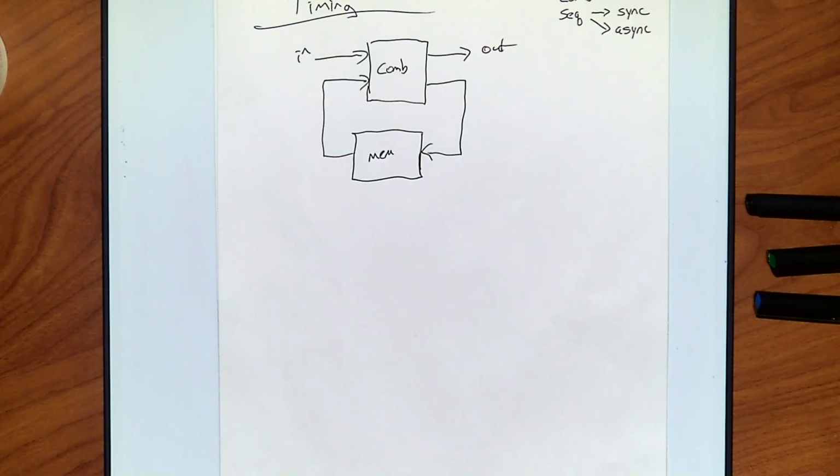So in essence, that XOR becomes a flip or not flip based on whatever the data line is. Usually you just add an XOR and you get a T flip-flop. That's useful for counters because when you're counting, something's constantly changing, so you can just send the T signal, which means keep counting. That's where they're typically used.